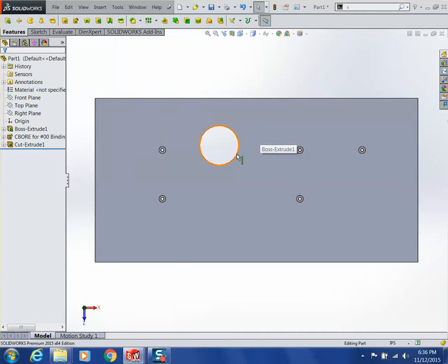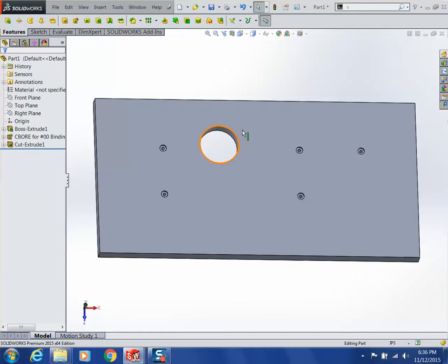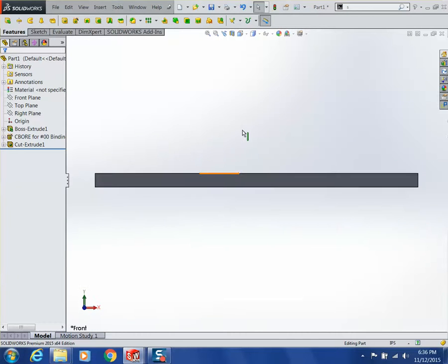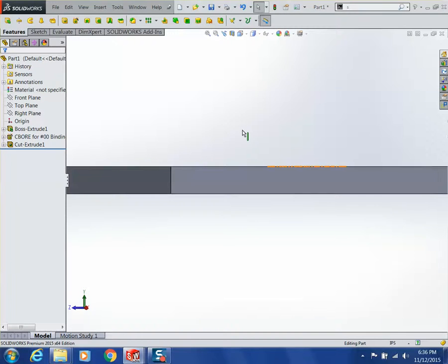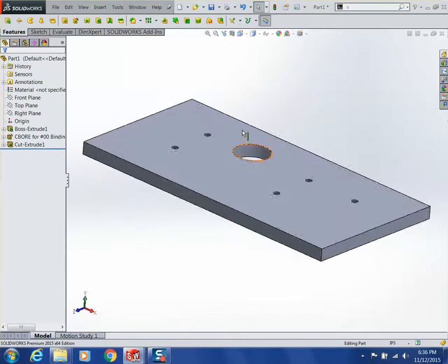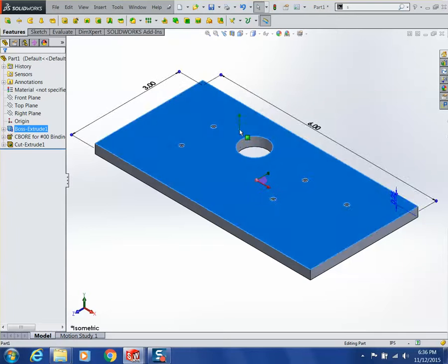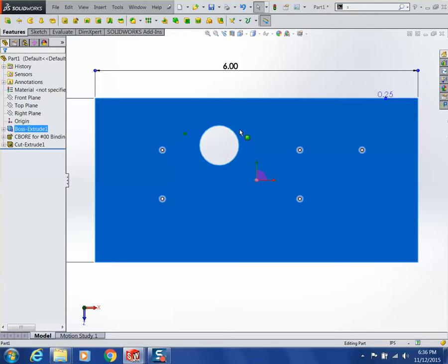In SolidWorks you have the option to do front, top, left, right, bottom, all those normal orthographic views of a part. You can also get an isometric and a normal to. Those are all on Control and then number keys. So Control 1 gets you front, 2 is back, 3 is left, right, top, bottom, ISO, and then normal to is 8. If anybody's a keyboard monkey like me who stays off the mouse whenever you can get away with it, those are huge.